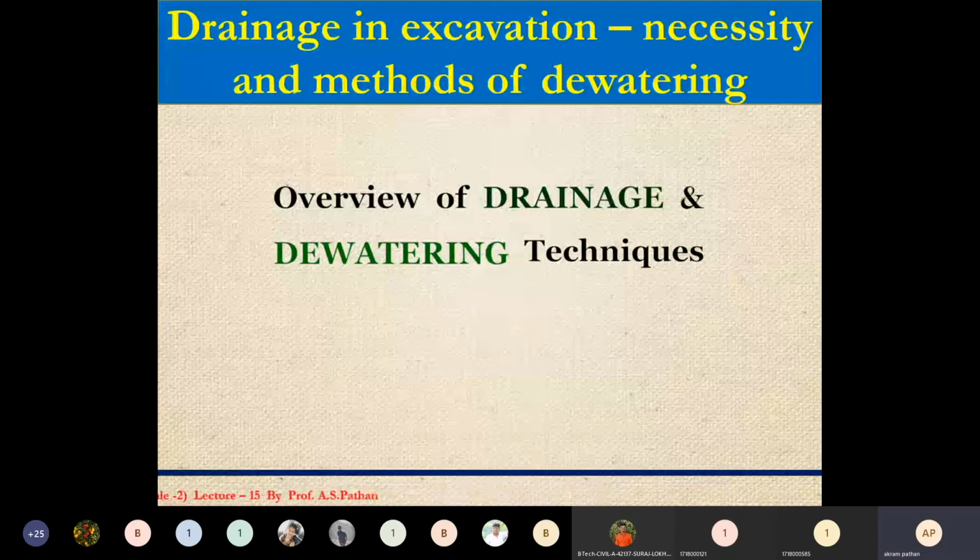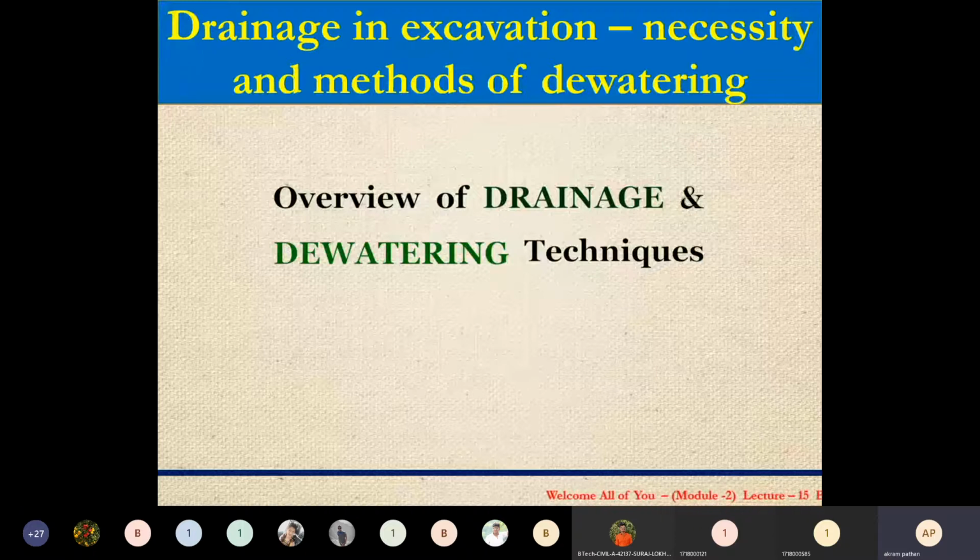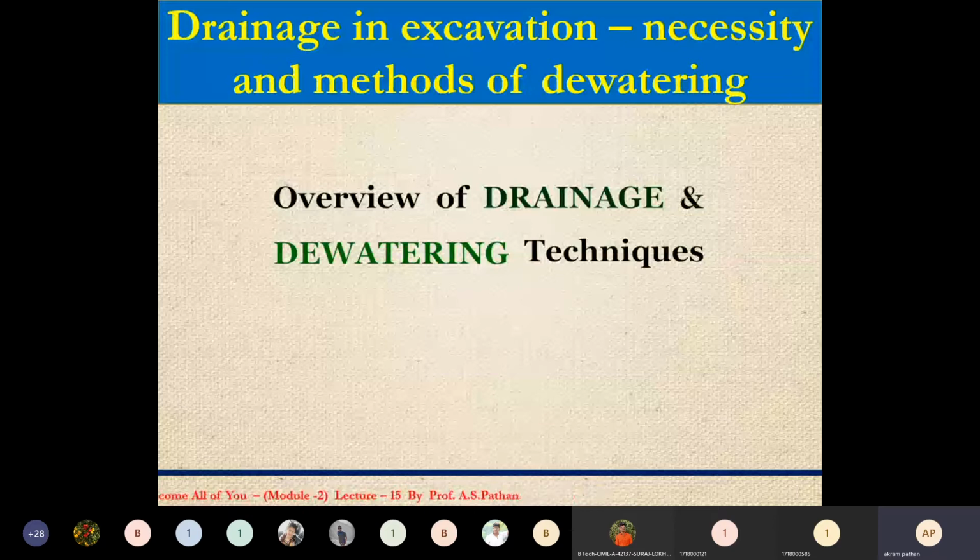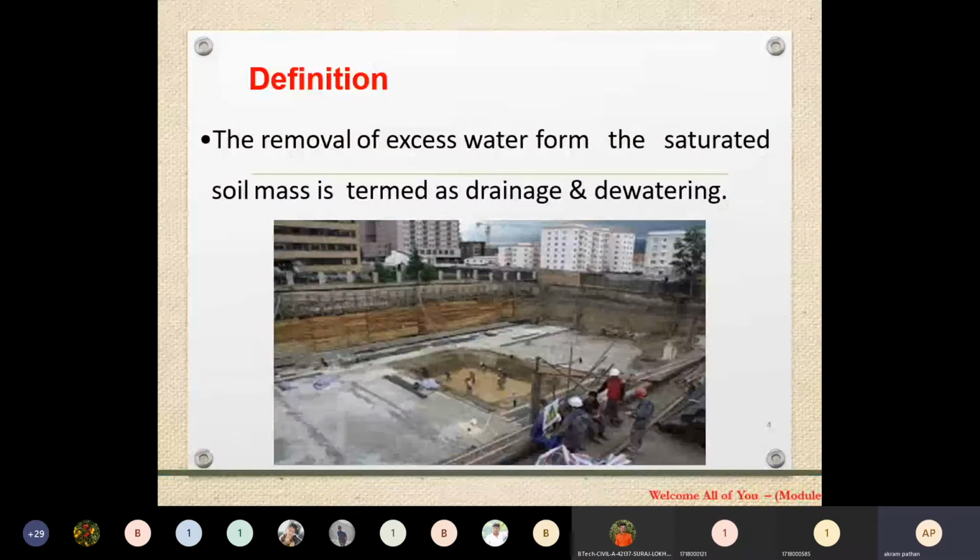Uncontrolled groundwater can flood excavated areas, damaging construction material and equipment. Water can also cause trenches to collapse and flood, threatening the construction workers in the area. Therefore, selecting an adequate dewatering method based on soil conditions and water table is an important step before the construction of any foundation.